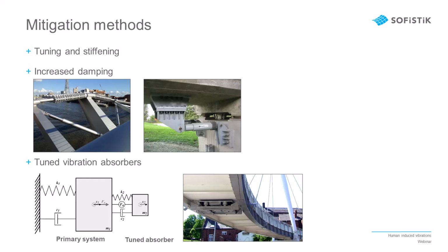There are also external systems that can be incorporated within the structural system, either at the design stage or as a retrofit to aid the vibration control, like viscous dampers. The external dampers can be incorporated in bearings and supports or as a thick layer of high viscosity asphalt for the bridge surfacing. External dampers were retrofitted to the Millennium Bridge in London, as shown in the photo, which solved the lateral sway vibration problems entirely.